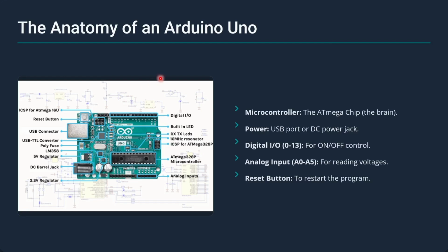This is the standard Arduino. We will also get clone Arduinos, which will be cheaper for your project. There is a built-in LED which will blink continuously. Suppose the Arduino is not blinking when the program is uploaded, then we should think it is dead, or we need to burn the chip using the burn bootloader.